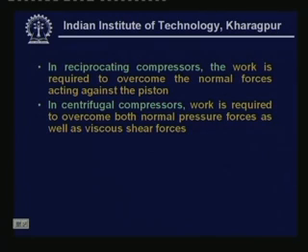Whereas in centrifugal compressors, work is required to overcome both normal pressure forces as well as viscous shear forces. So, here the refrigerant has to flow against an increasing pressure. So, you have a normal pressure acting on the refrigerant. In addition to that, it also has to overcome viscous shear forces. So, the work input is required for these two purposes.